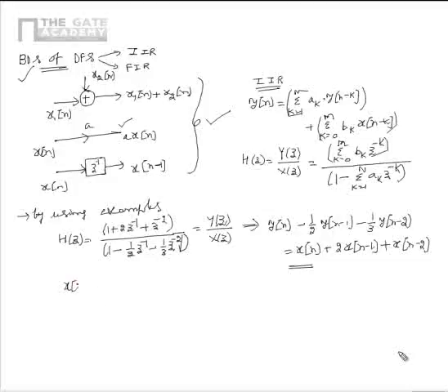Suppose the input to the filter implementation is x of n. We see that we need to realize the terms x of n, x of n minus 1, and x of n minus 2. So we need to add delay elements as shown in the figure, which are mainly to produce x of n minus 1 and x of n minus 2.